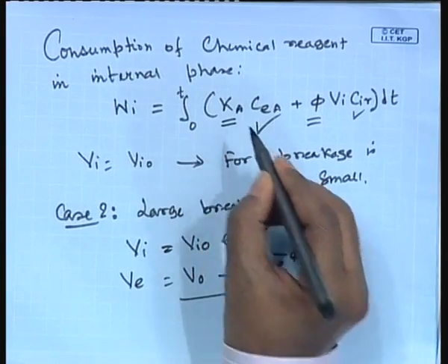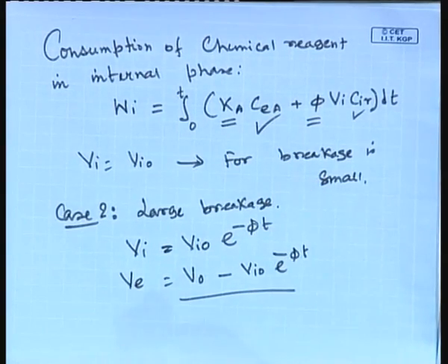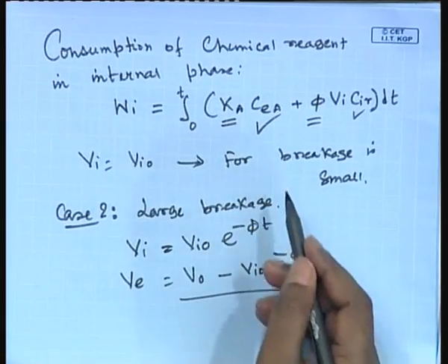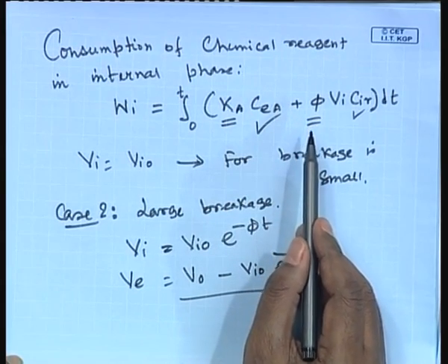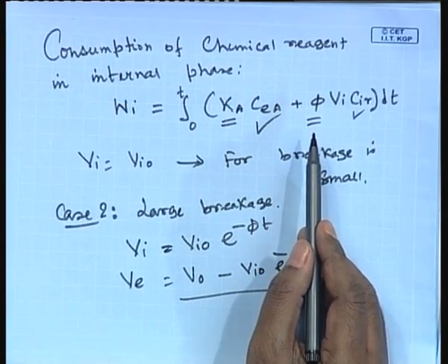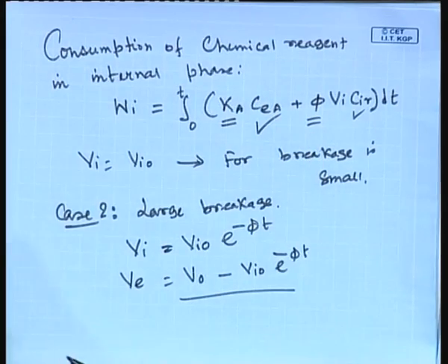So, you do not know the values of phi and K a priori. Okay, you do not know these values. So, what you have to do? You have to do small scale experiments for a particular system and get the concentration profile. That means, you measure the concentration of the particular reagent in the external phase, get the concentration profile, and then you know the numerical solution, the analytical solution. So, you start with a guess value of K_a and phi, these are the parameters, and calculate the concentration profile theoretically with the guess set, and check whether this calculated profile matches the experimental profile or not.